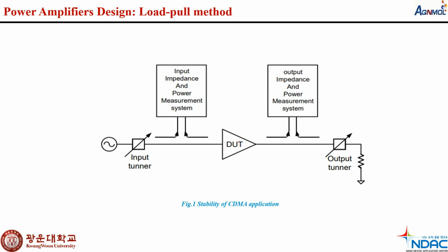Automating this process is crucial due to the many test conditions that need to be verified, such as input signal, bias and frequency, for example. And finally the benefits. It provides the data for optimal load selection considering performance trade-offs, and it is also useful for active device model extraction and verification. There are some challenges as well: it requires an automated load pull measurement bench, and selecting the right physical device to avoid complex de-embedding procedures. These are some of the challenges in this load pull method.